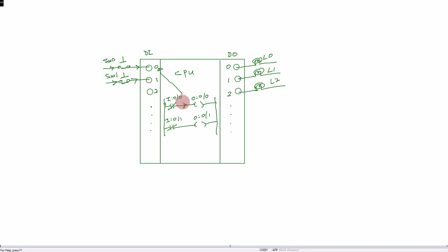So the virtual power or virtual current will flow through the rung and energize the digital output, which is a virtual output coil. Because of this, it will cause the digital output 0, which is terminal point 0, internal LED to be energized. Because the digital output internal LED 0 is energized, it will cause its internal normally open switch to be triggered from normally open to close. Thus, the current can flow through the circuit and cause the light 0 or the lamp 0 to turn on.